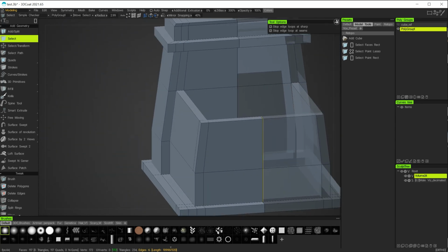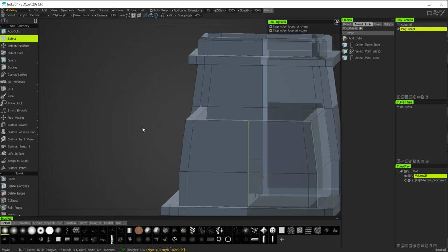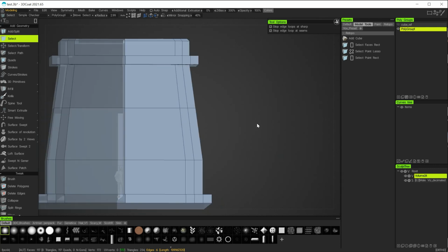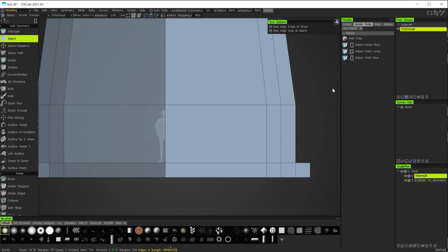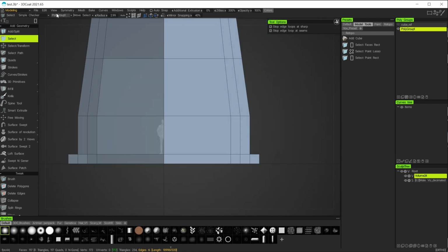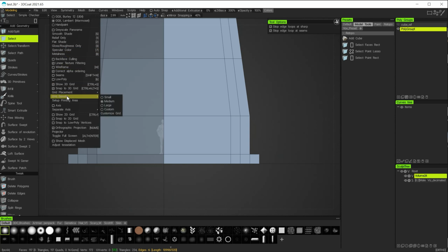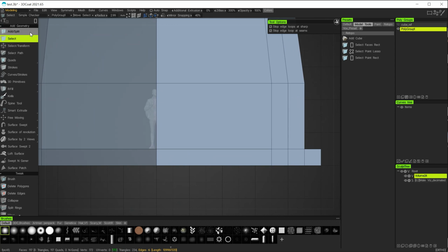So what we'll do now is we will just take a look, and what's next to do, we'll create the doorway next on here properly. So I'll go to the front view here and use my grid again. I'll need the other grid plane visible. So let's go over to turn the YZ one off and turn on the XY, just so I've got some sort of measurement here. And then I'll go over to my split tool again.